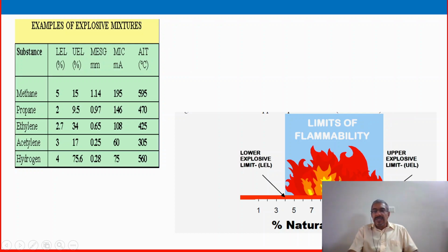In between this limit, a hazardous situation can always form, and if methane is present in this condition, a fire can happen anytime when a source of heat or a fire triangle forms. So 5 to 15 is the range of methane.